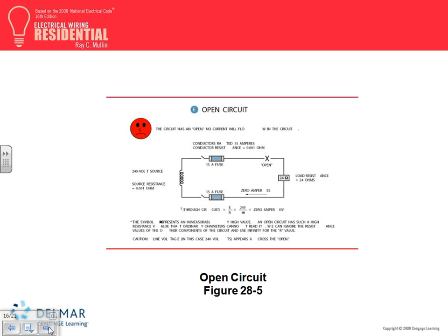These are the stages of a circuit, guys. Open circuit. If you have a circuit, one thing could happen to it. Ben, that's what happened to your circuit in your house. You have an open circuit condition. The neutral is open. What happens if you have an open circuit condition? If you have an open circuit on the hot, nothing will work. If you have an open circuit on the neutral side, also nothing will work. If you have an open circuit in a multi-wire branch circuit and you lost the common neutral, now you burned equipment. So that's an open circuit condition.